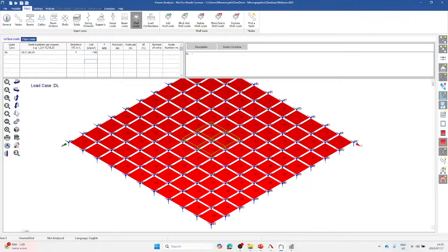And from there, I'm not going to add in any load combination. There is no particular reason why I'm not doing that. You can definitely add in different load combinations, be it dead load only, and if you wanted to apply live load, you could have done that. But remember, this is just a guide for today's webinar. I'm just doing step by step guidance on how to model your spring elements within Prokon Frame, right?